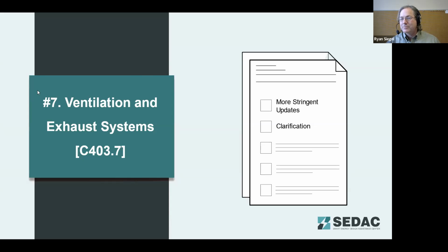I also had a question here about are dry bulb economizers still allowed? Yes, you can use any style of economizer. It could be dry bulb, differential dry bulb, enthalpy, or differential enthalpy. There's a table in the IECC of what requirements are for specific set points for each of those in the economizer section. But yes, you can use any style of economizer.